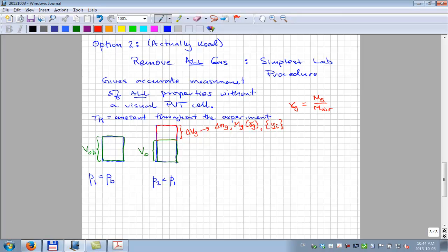So what's actually measured? Let's put something pink around that. That's actually measured. It's like a standard condition gas meter. If you have volume at standard conditions, you know the moles, right? The 23.68 number converts from volume in liters to moles.